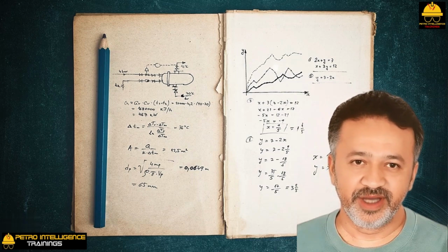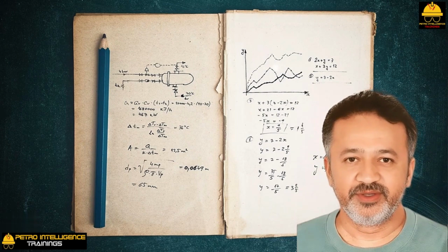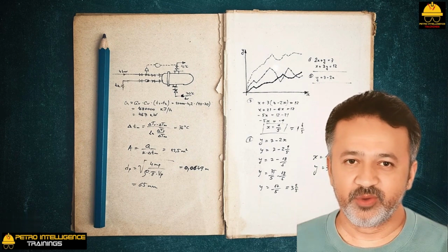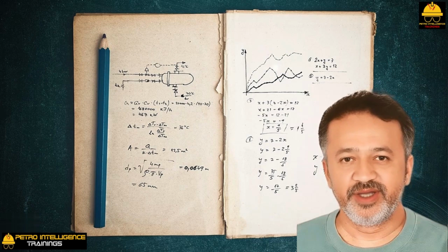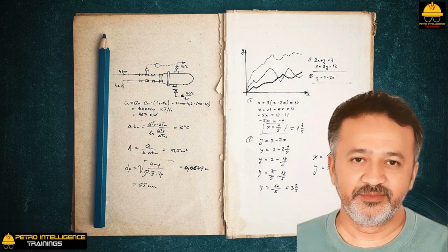As the steam is expanded to a lower pressure, the moisture in the supply steam will evaporate and cool off the steam, thus reducing the amount of sensible heat that could be converted to steam velocity.